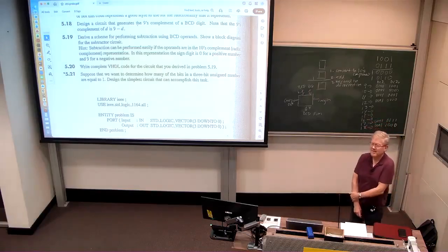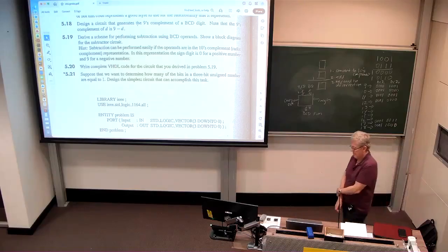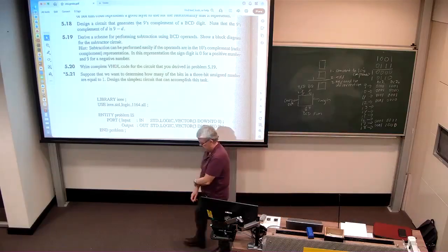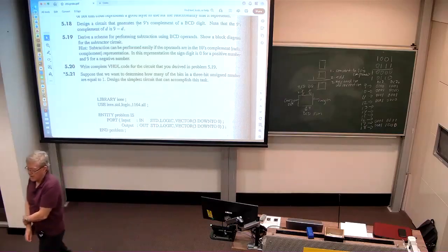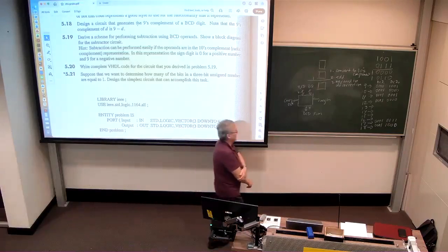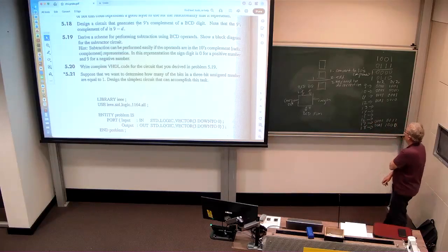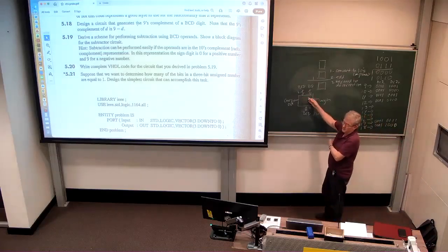Right. I'm thinking about displaying on the hex though, because if we're outputting a full BCD sum, then it'll always be between 0 and 9, that BCD sum, right? Because your circuit has to correct for the fact that if it's more than 9, what should it be? Subtract 10, yes, effectively. Right. So what's the best way of figuring out what the logic should be in here?